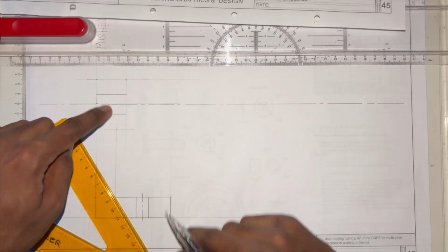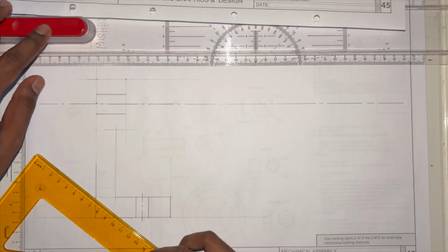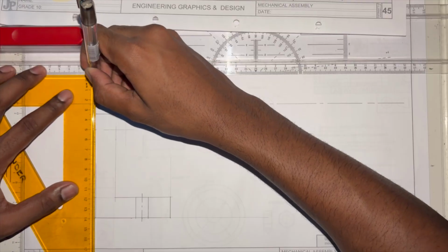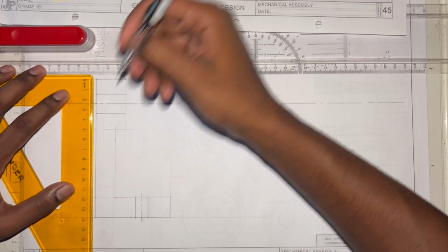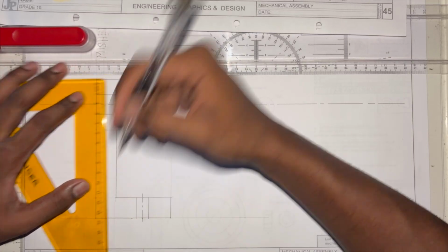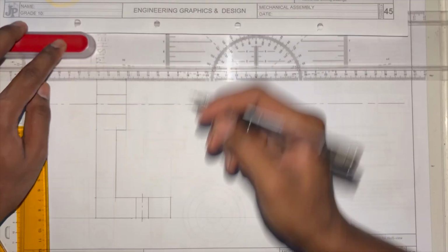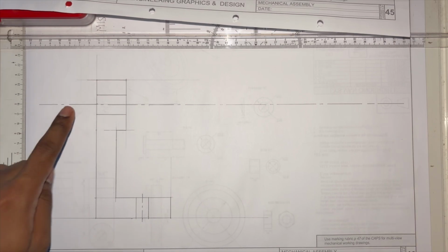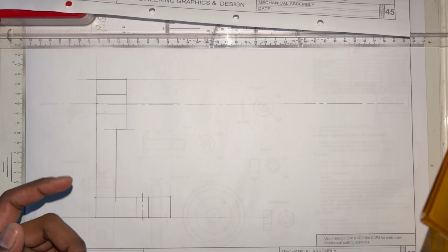Okay, this is where the shaft is going to go through. There we go, nice and neat. You don't have to erase this construction, leave it. It stays there, it's fine. Make sure you have your center lines. Make sure you have both of them drawn in. Make sure these are not hidden detail, because when you cut, it changes to solid, because you're looking at the material.